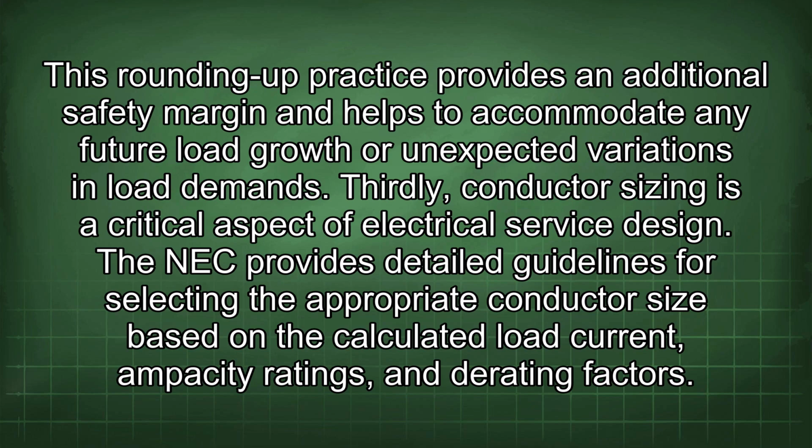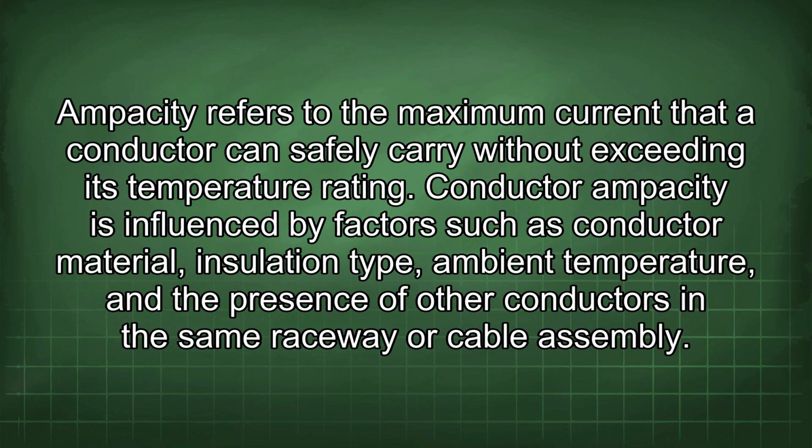Thirdly, conductor sizing is a critical aspect of electrical service design. The NEC provides detailed guidelines for selecting the appropriate conductor size based on the calculated load current, ampacity ratings, and derating factors. Ampacity refers to the maximum current that a conductor can safely carry without exceeding its temperature rating. Conductor ampacity is influenced by factors such as conductor material, insulation type, ambient temperature, and the presence of other conductors in the same raceway or cable assembly.